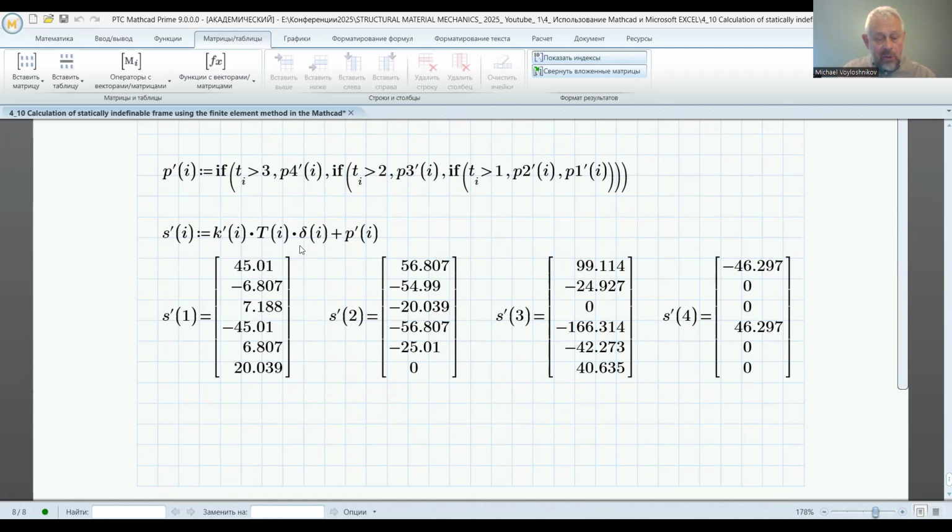These together two factors mean the displacement of the ends in the local coordinate system. This is longitudinal displacement, transverse displacement, and angular displacement. This is the result of the product of this matrix onto the array of vectors. And as in the global coordinate system, this together we consider as a delta stroke displacement in the local coordinate system.